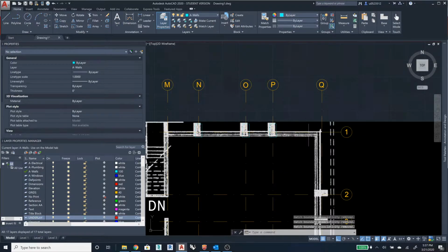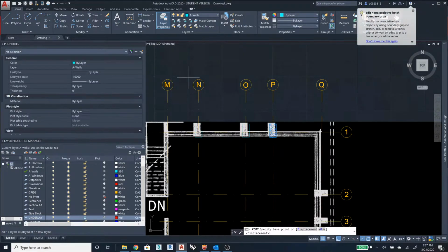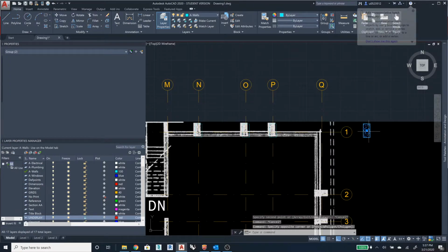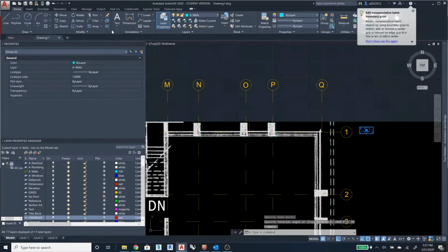Okay, now we've started drawing. So I'm going to copy those all the way around. If I copy another one out here for this other elevation, and I want to rotate it, just type in the rotate tool, make your selection, hit a reference point, and then it'll orthogonally change to each cardinal direction. Or you can just type in 90.